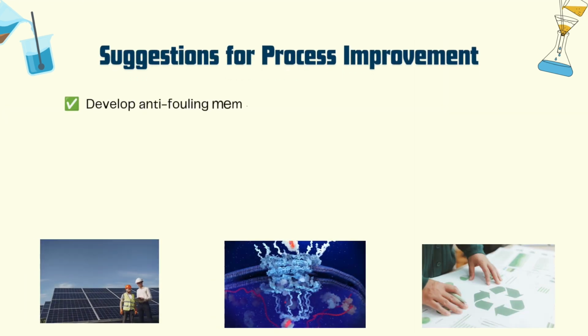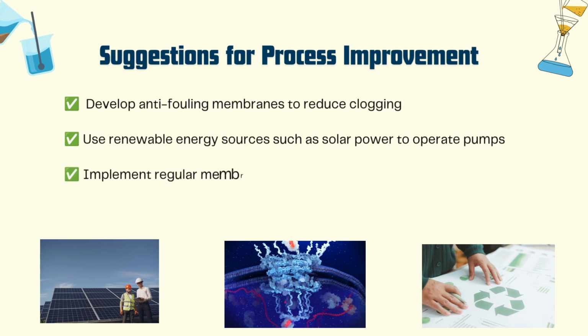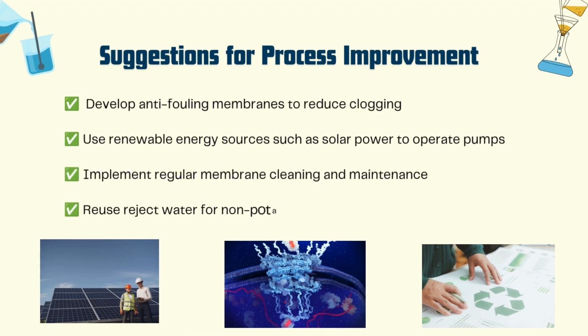Several improvements can enhance the ultrafiltration process. Anti-fouling membranes can reduce blockage and improve efficiency, while renewable energy such as solar power can lower energy consumption. Next, regular maintenance helps extend membrane lifespan, while reject water can be reused for non-drinking purposes to minimize water wastage.